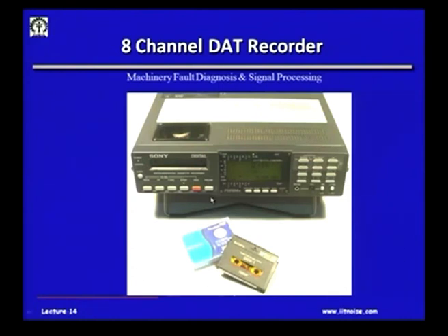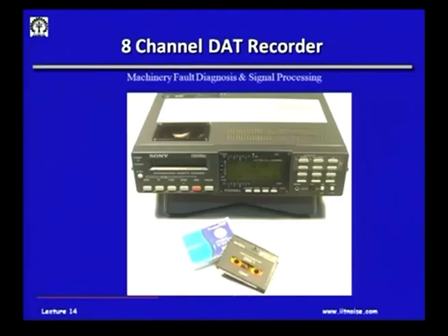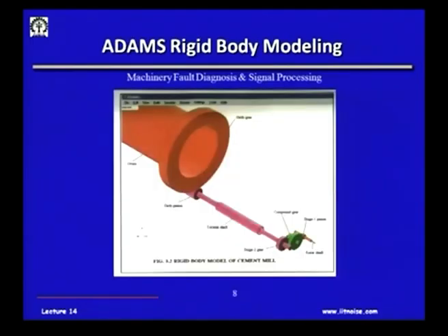You can record them on the tape, because in such a dusty environment, we cannot, if you go to that plant, there is a lot of cement dust everywhere. We cannot be putting computers and sophisticated equipment and doing an analysis in an area of cement dust. So, all you do is record them on that media, bring them to the lab, and then use your software, MATLAB. You can do FFT, and then do this Cepstrum analysis as per the algorithm I just mentioned.